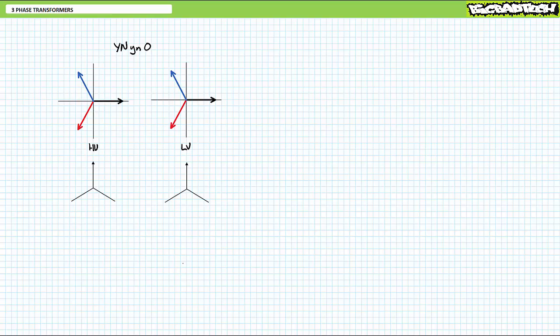Since the low voltage side of a YN/YN0 configured three-phase AC transformer is perfectly in phase with the high voltage side, the low voltage side phasor and displacement diagrams are essentially repeats of the high voltage side, i.e. the reference phase pointing at 0 degrees on the right-hand side of the phasor diagram, and the reference phase indicated as an arrow pointed straight up at the top of the displacement diagram. Like I said, the displacement diagram is essentially a phasor diagram, only rotated 90 degrees counterclockwise.